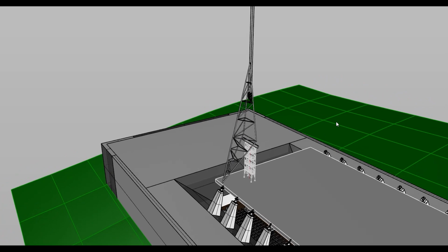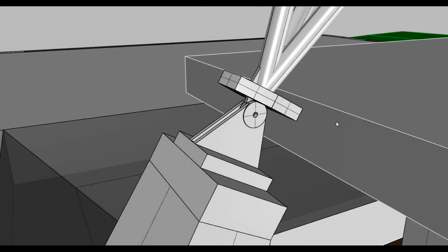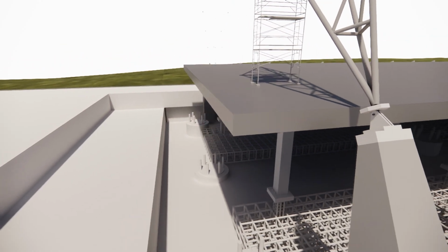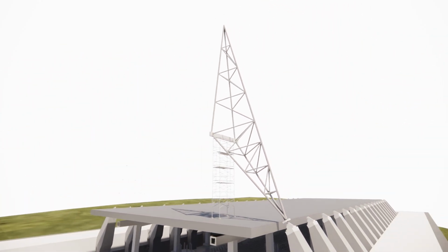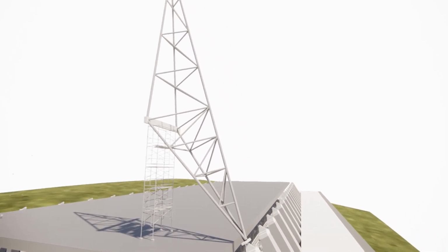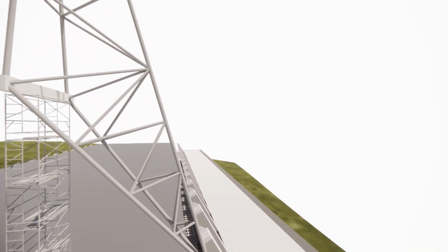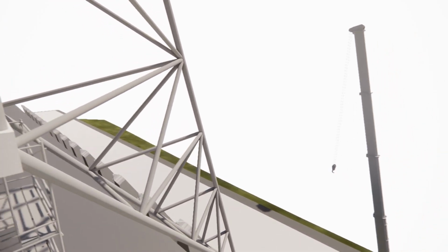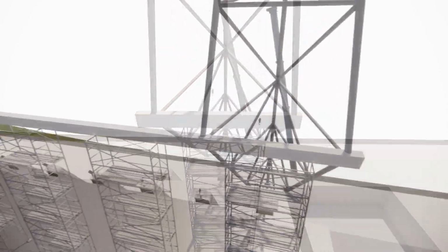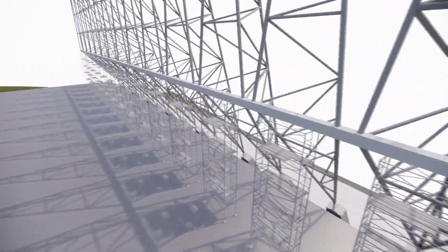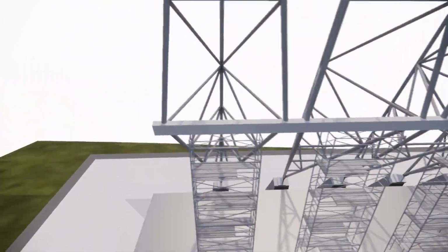When cranes brought the tetrahedrons near, people both below and above performed welding and bolting to secure the tetrahedron with the beams and hinges. The support base was fixed using bolts as previously described. The initial assembly involved bolting to temporarily secure the pieces, allowing for adjustments and alignments before final welding was completed, to permanently fix the structure in place. This process was replicated on both sides for all 17 units.